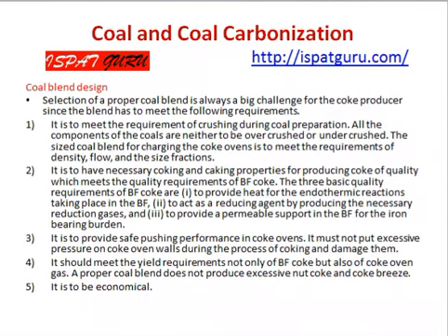BF coke. Three basic quality requirements of BF coke are to provide heat for endothermal reactions taking place in the BF, to act as a reducing agent by producing the necessary reduction gases, and to provide a permeable support in the BF for the iron bearing burden.